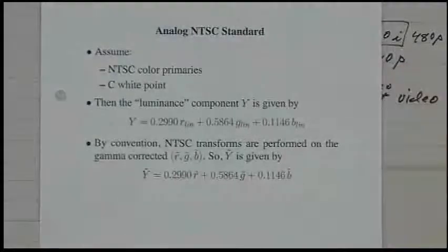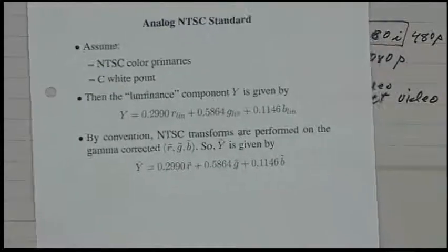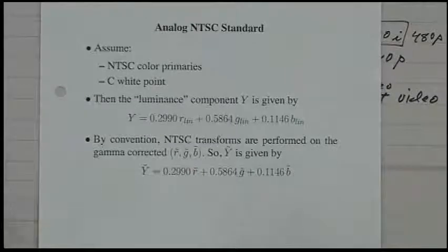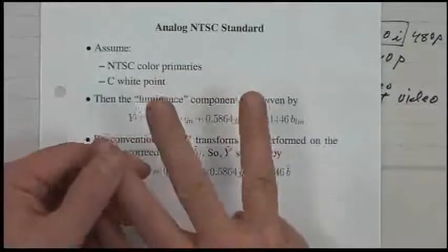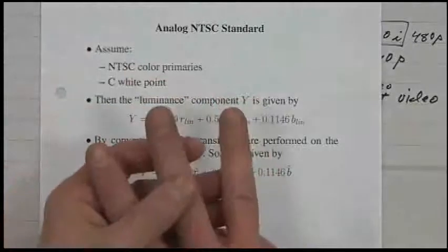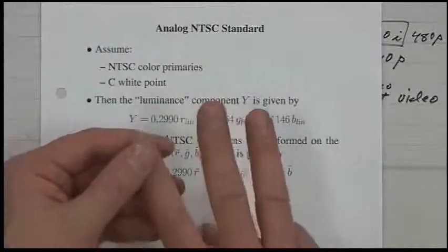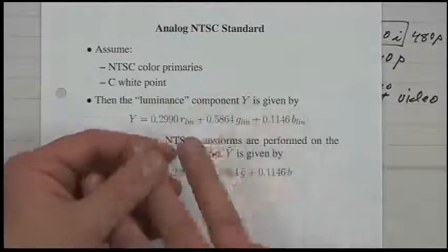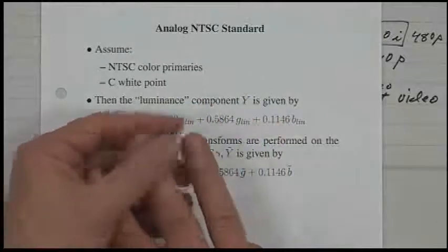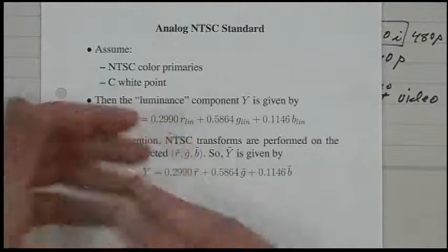So the point is, you're going to have the so-called black and white, and the chrominance components. So there's three components, right? You have red, green, blue, right? But we're going to transform that to another system which has the brightness, the achromatic component, and then the two chromaticities that you add to that to essentially colorize the image.